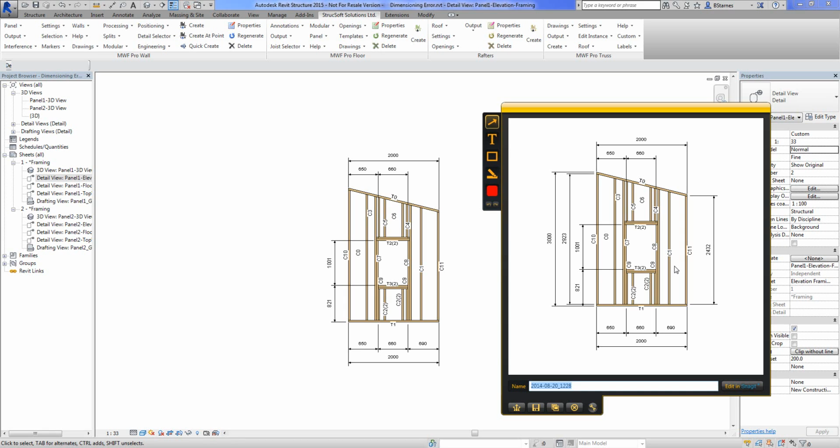Lastly, work plane. I mean, it's not obvious, it's not that apparent that a change to our work plane could have a trickle-down effect on our shop drawings, but we could see that what would look like an indirect change all of a sudden has an impact on our shop drawings. So let's be careful. Again, if we keep in mind, save our shop drawings to the very end, we wouldn't be playing with work planes, and we wouldn't be having any issues.